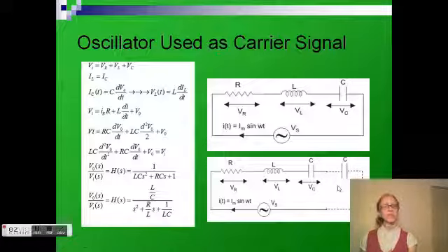I attempted to counteract the resistance added from the wires by incorporating another capacitor in series. Capacitors in series combine like resistors do in parallel. Therefore, you could decrease the capacitance, and decreasing the capacitance would allow you to counteract the increase in resistance. I tried to avoid including more inductors as much as possible, although I considered adding one in parallel, because inductors can be very, very large. You can use ferrite beads to make up for this, but they are very expensive.